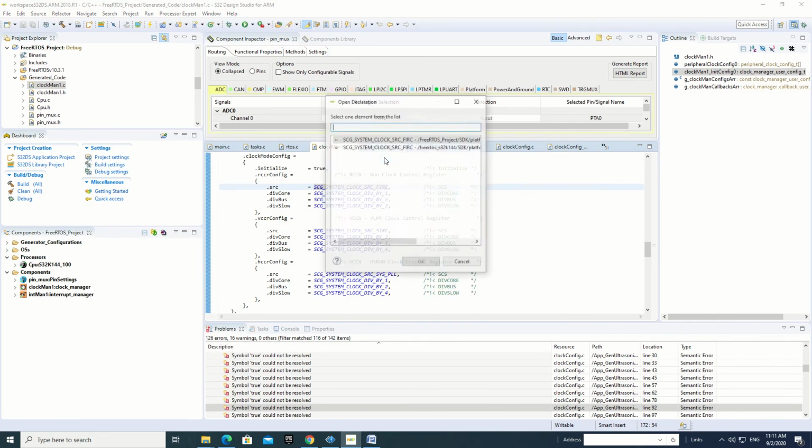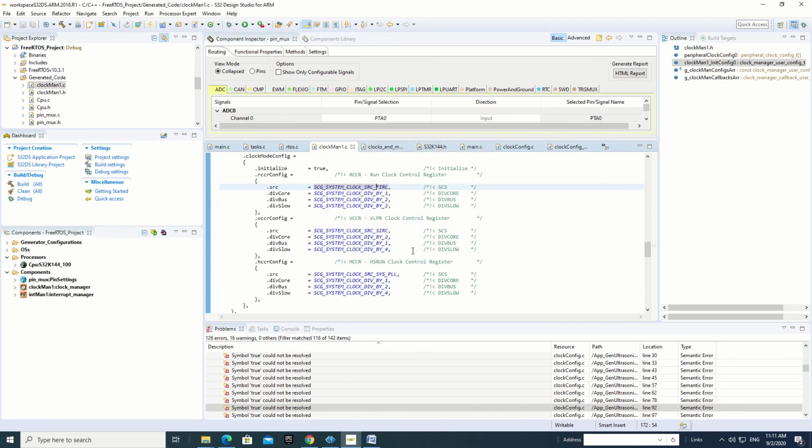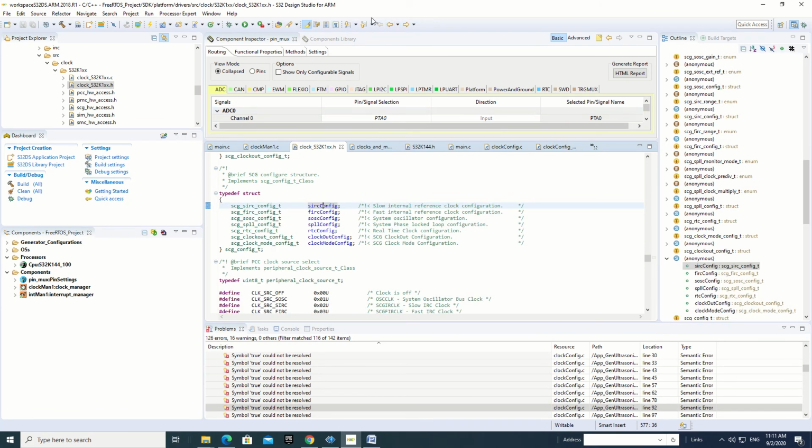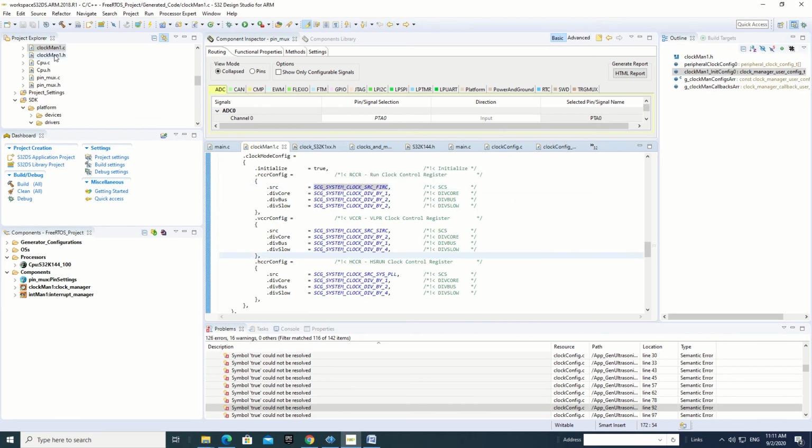We can go upwards and select the clocks here. We can use this one, 6, and then we will get this SPLL clock. These are also the same dividers, divide by 1, divide by 2, and then here it is divided by 2 again. So this is another configuration.